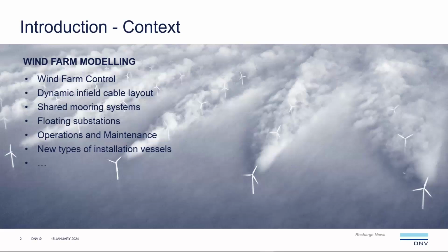I'd also like to mention wind farm control, because this has recently received quite a lot of attention. There's a joint industry project, led by DNV, looking at validating some of the models that have been developed for many years, looking at interactions between turbines with the objective to maximize the energy captured by the whole array. So here we're looking at the array as a power plant instead of looking at each individual unit.